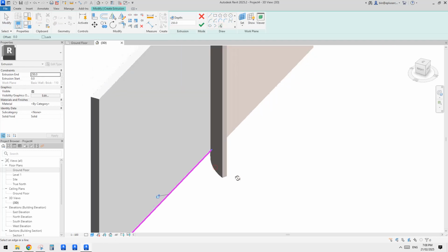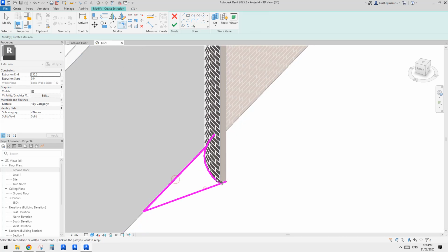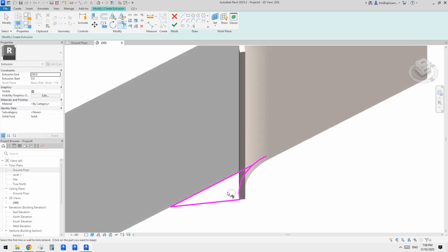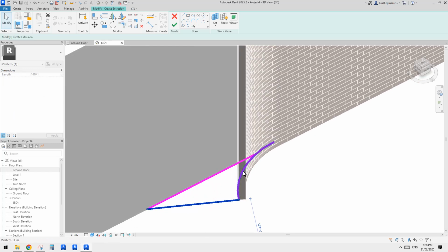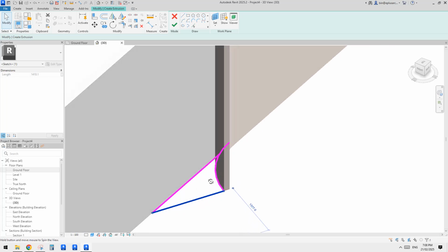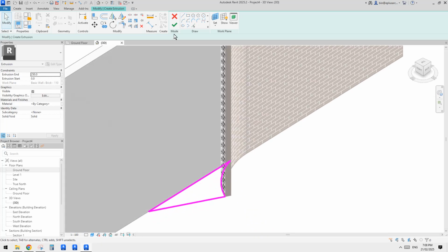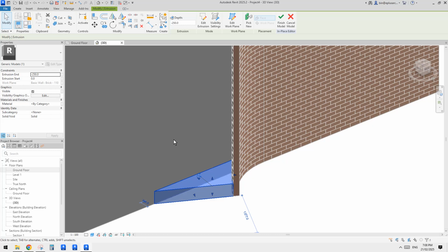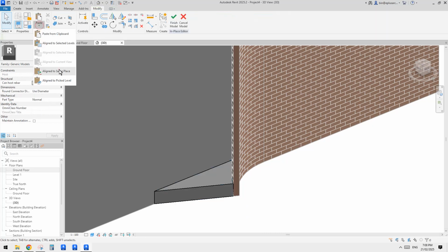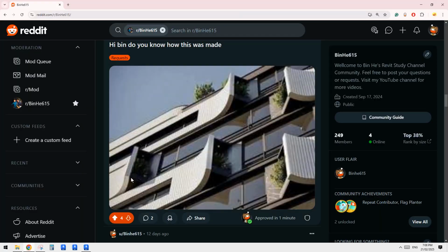For example, I'll just pick this wall and pick maybe this direction. So maybe I'll just do something like this, right? And if you want to, you can also constrain. You can align the lock onto surface, and also trim this, and then you can just give it a thickness, maybe -250, something like that. And I'll just do Control C and then paste in the same place. Edit extrusion, or just use offset, because it's a planar box.